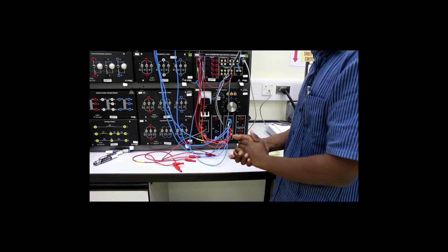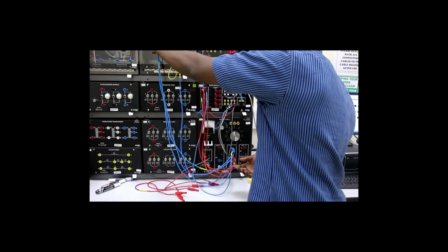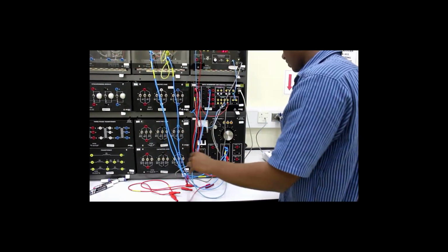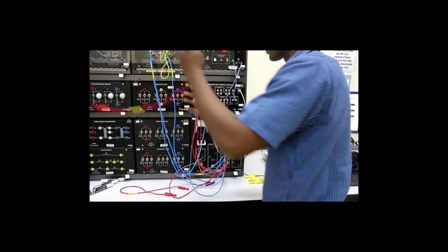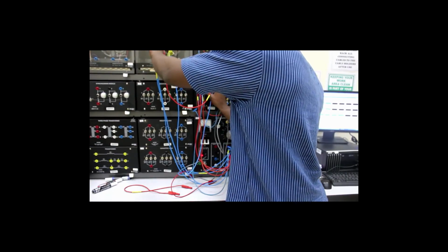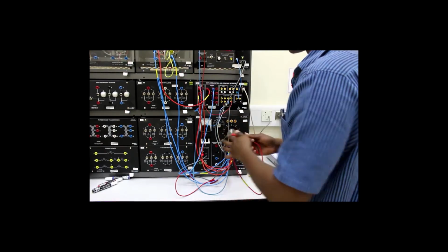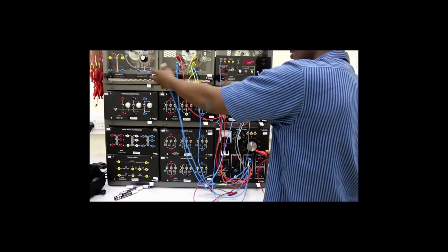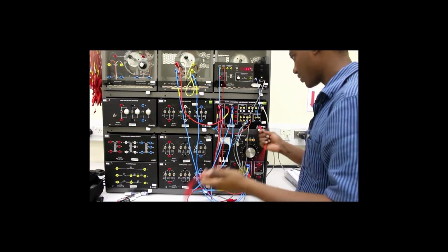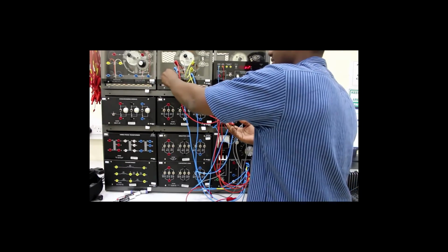We also would like to measure the line current, so we're going to connect it in series here, with the winding. So we got I1, and the same thing for I2. I'm going to connect it to the third phase just to follow the diagram given in the report manual. That's it.